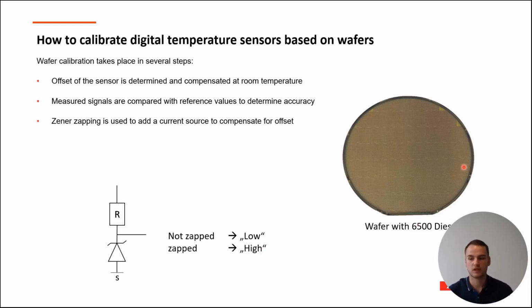This 8-bit signal allows the logic in the sensor to read this value, and for each value, once again from 0 to 256, a resistor is switched on to influence the voltage drop across the capacitor, which I showed you in the slide before. The capacitor generates the duty cycle as an output signal, and if we have a higher voltage drop on the resistance on the capacitor, then the capacitor will be charged faster, and therefore we can improve our accuracy because the capacitor will be charged a little faster.